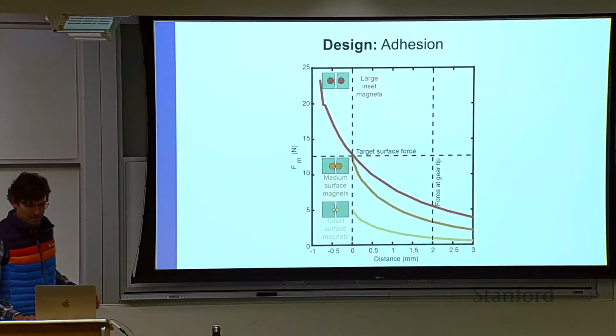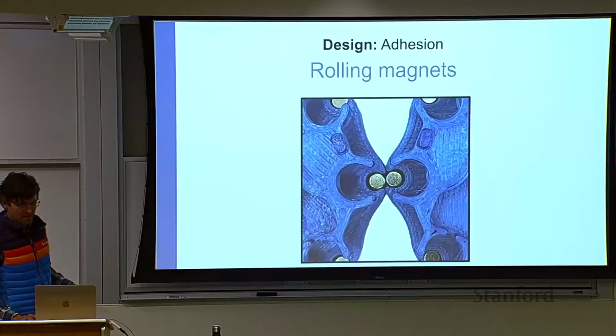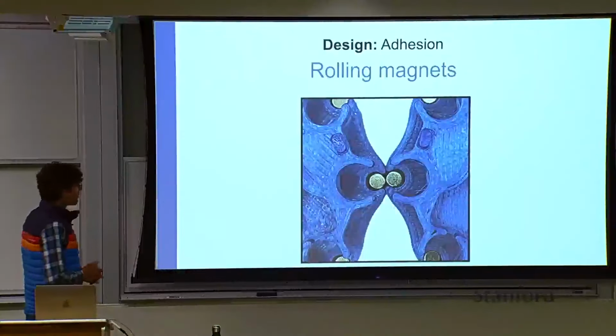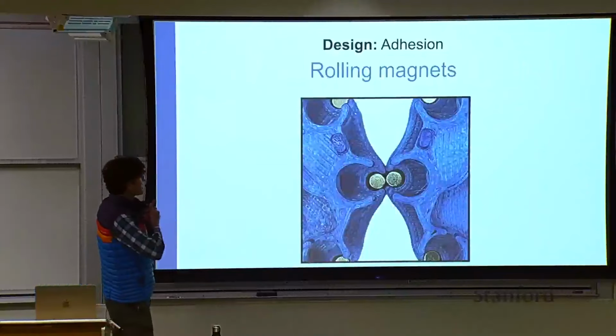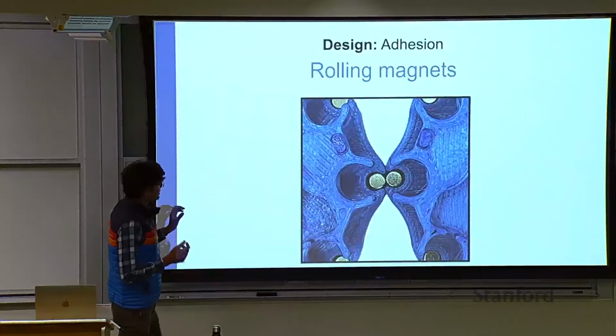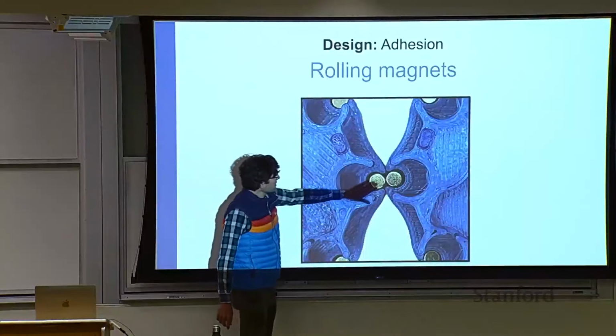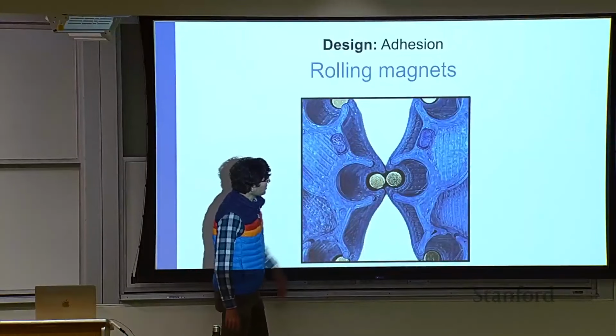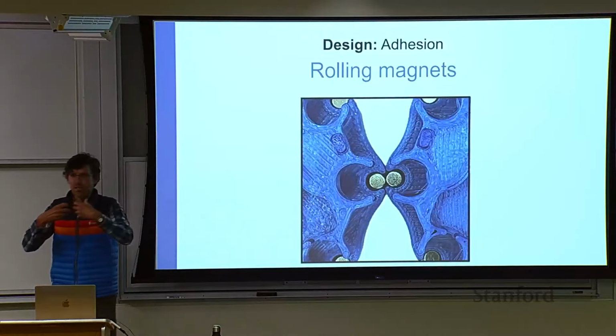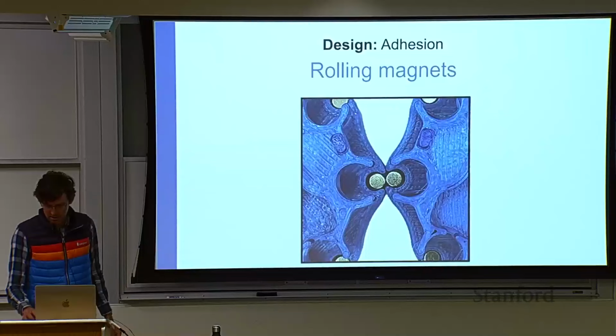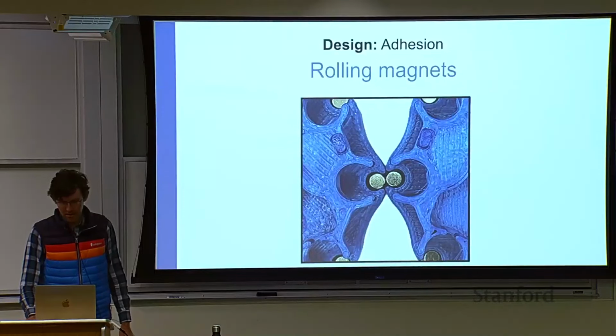So we chose that medium magnet for our robots, and we want any two robots to touch and connect. The magnets are not glued in place; they're floating in this little holder, so the magnets can just rotate around to any orientation they need to match with the nearest neighbor.